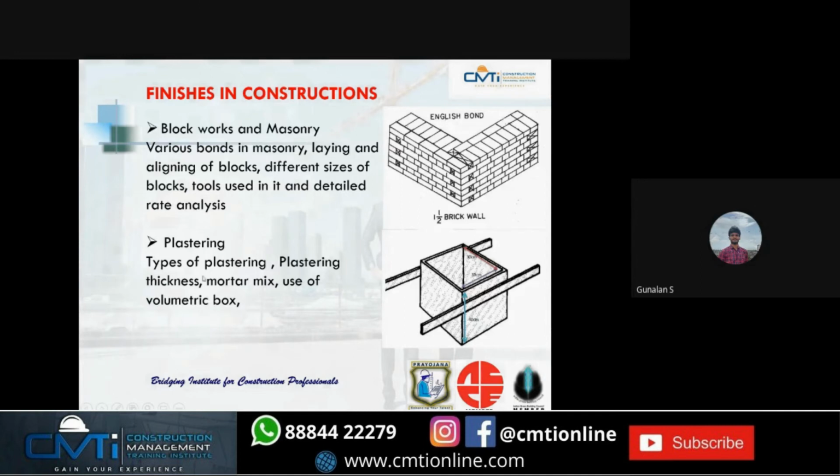Next, plastering. There are two types of plastering: gypsum plastering and cement plastering. Gypsum plastering gives a smoother finish compared to cement plastering. Plastering thickness is determined based on the requirement, and before plastering, a wire brush is used on the surfaces of the walls.